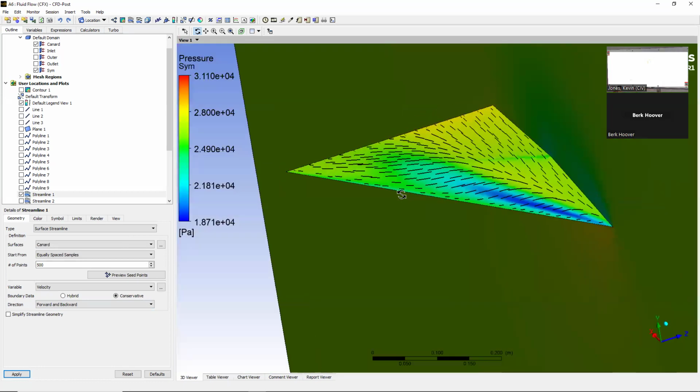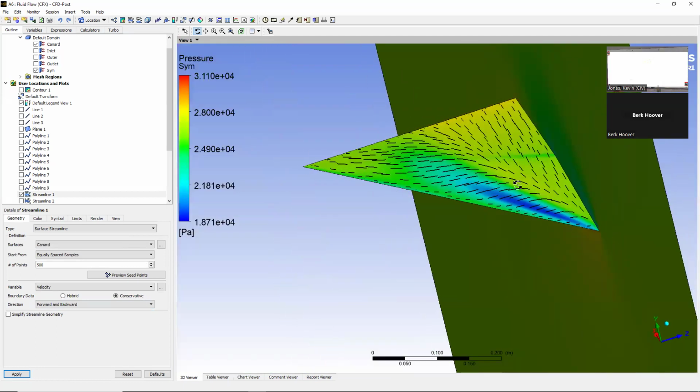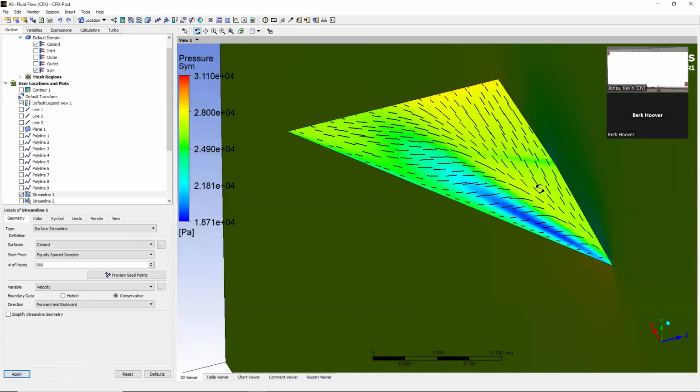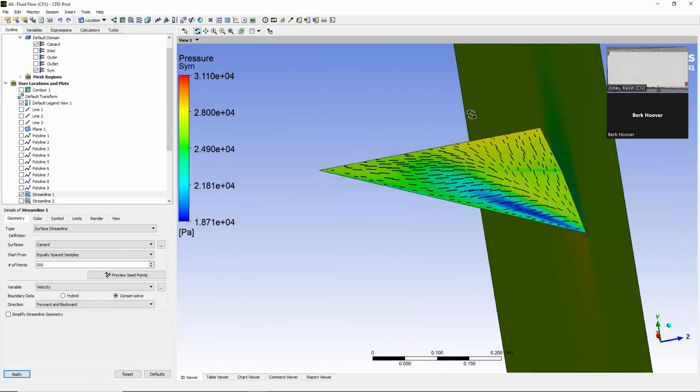But anyway, you can see what the surface flow looks like going along there. So here's the big vortex. You can see it's making huge cross flow velocities in there. And then this one, we didn't go to high enough angle of attack, but if you did, in this region is where you're likely to see stall. This is the higher pressure, so it's less useful for producing lift.